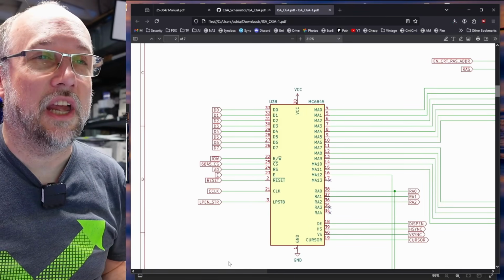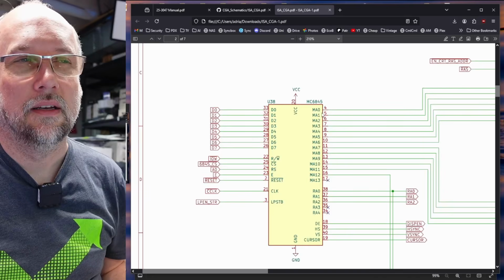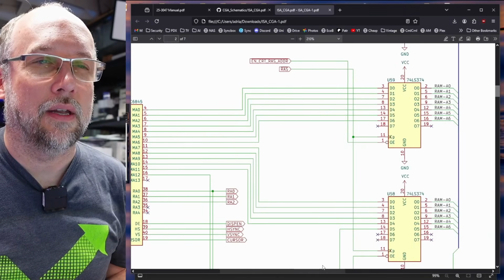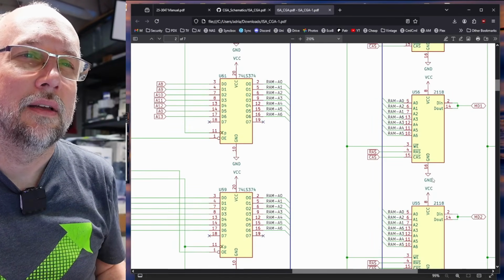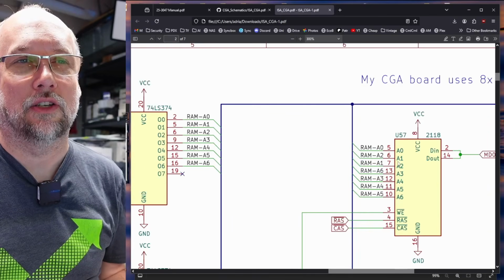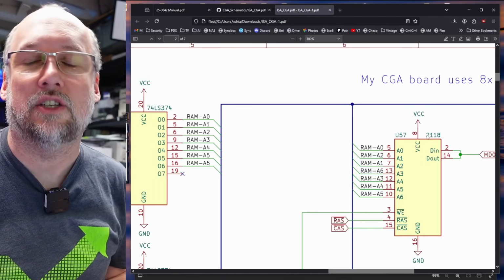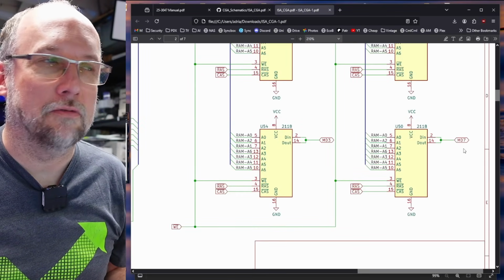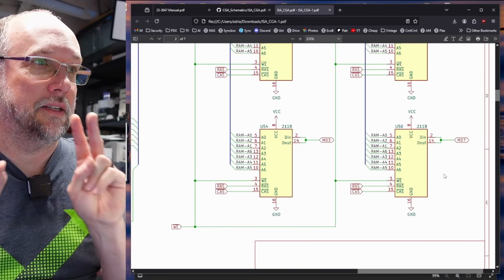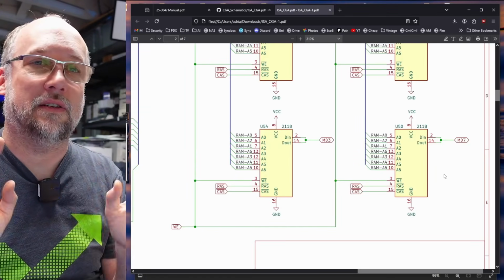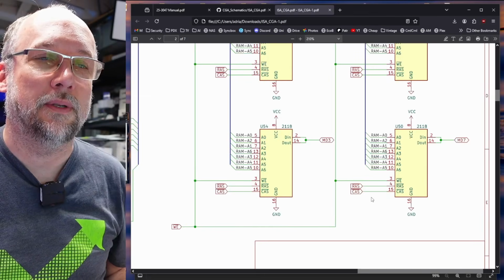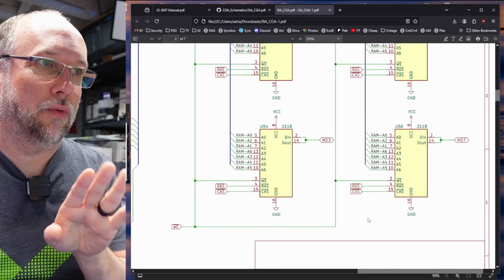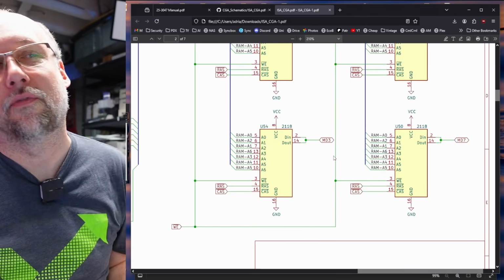All right, so here on the CGA card, we have the 6845, that's the CRTC. Really, this is handling all the memory address lines. That's the MA lines here. And if we follow these, they go through some latch chips, and then they're going to make their way over to the actual memory that's on the CGA card. It happens to be these 2118 chips on the original IBM CGA card. So the CGA card itself looks like it has 8 RAM chips. So even though it's working in a 16-bit fashion, I think, with the odd and even bytes as well, it's doing that with just 8 chips. It seems that this card, because this is requiring all of these 4 chips to be installed, is actually working in a 16-bit fashion. So it's obviously a little bit different than this card.